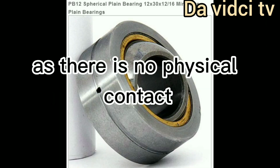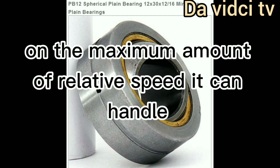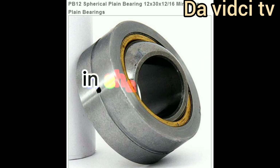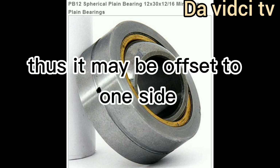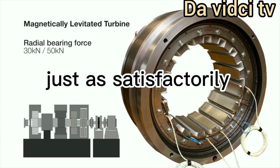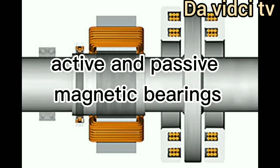As there is no physical contact, magnetic bearings are zero-wear bearings. There is also no limitation on the maximum amount of relative speed it can handle. Magnetic bearings can also accommodate some irregularities in shaft design, as the shaft's position is automatically adjusted based on its center of mass. Thus, it may be offset to one side but will still function just as satisfactorily. They are broadly classified into 2 types: active and passive magnetic bearings.